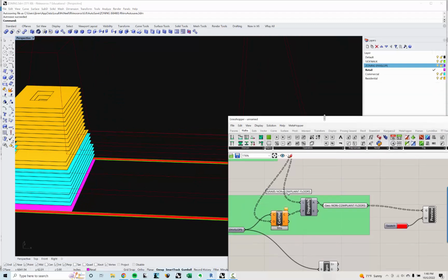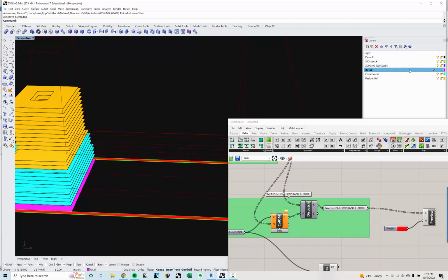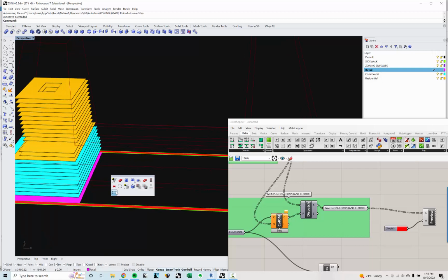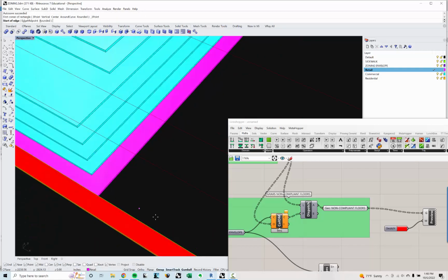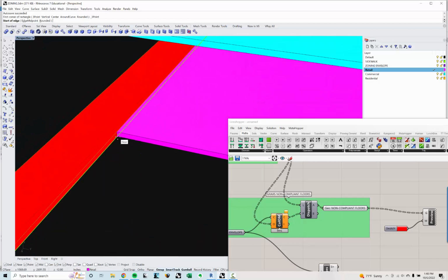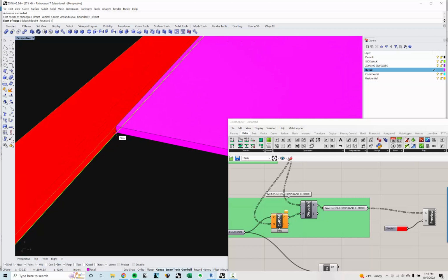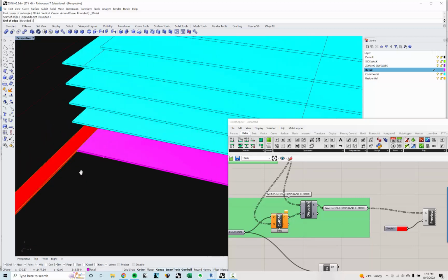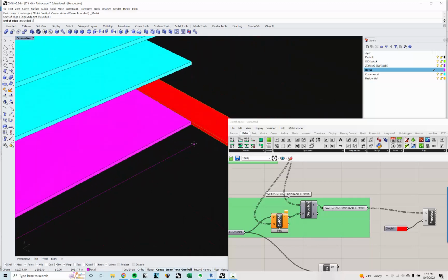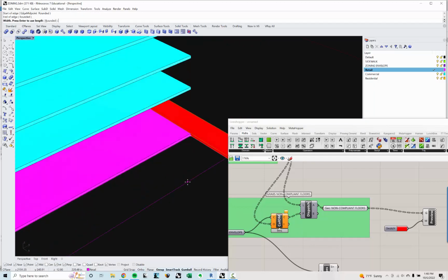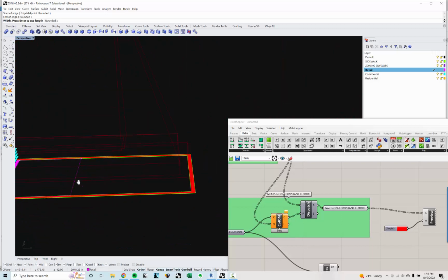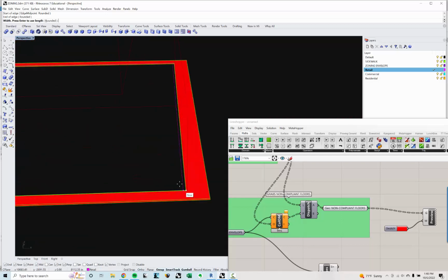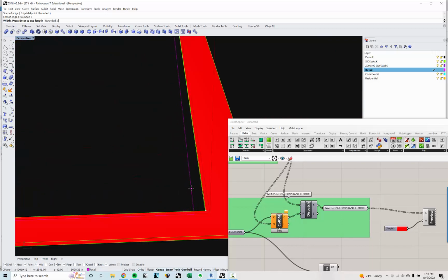And this is going to be pretty simple, but I'm just going to start modeling out some things like retail on the ground floor. So I can snap to, the one thing that's a little tricky about this is you can't snap to things that are in Revit unless you bring them in. So you might have to just eyeball it, or you can bake that component into here if you want to. You want to just make sure it doesn't get double counted. So let's just say we're going to do retail all along the whole entire ground floor here.